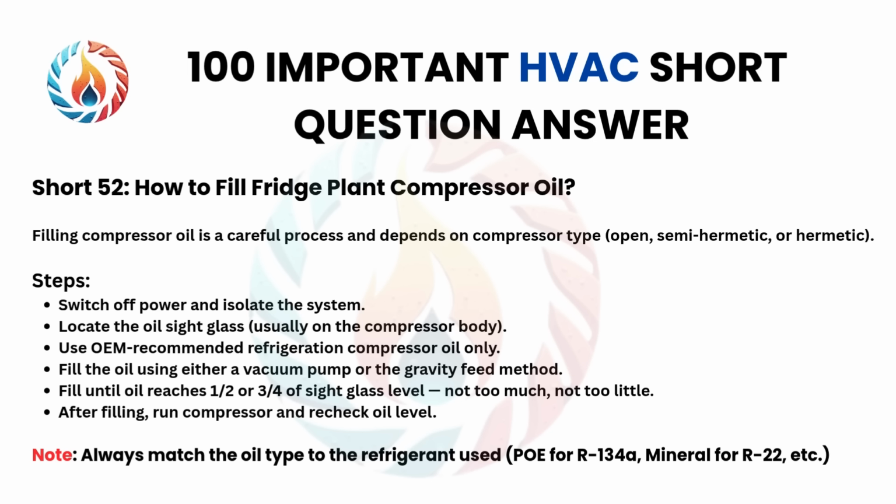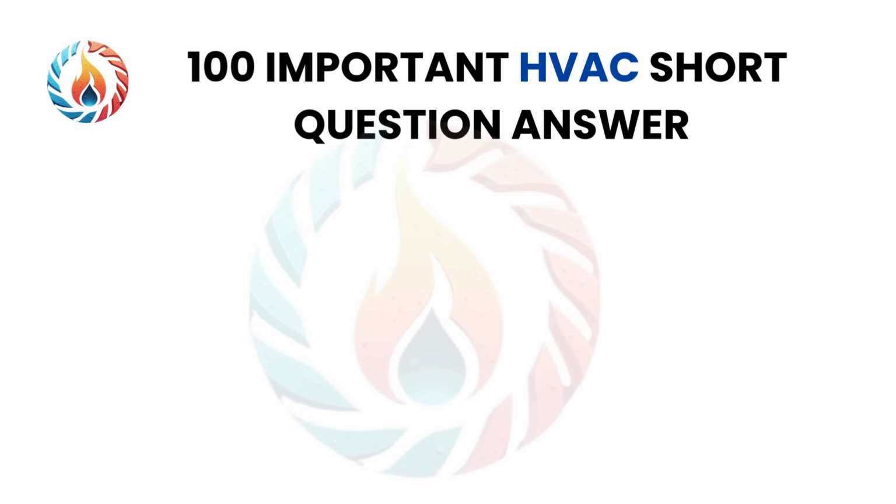Fill until oil reaches half or 3/4 of sight glass level. Not too much, not too little. After filling, run compressor and recheck oil level. Note: always match the oil type to the refrigerant used. POE for R134A, mineral for R22, etc.